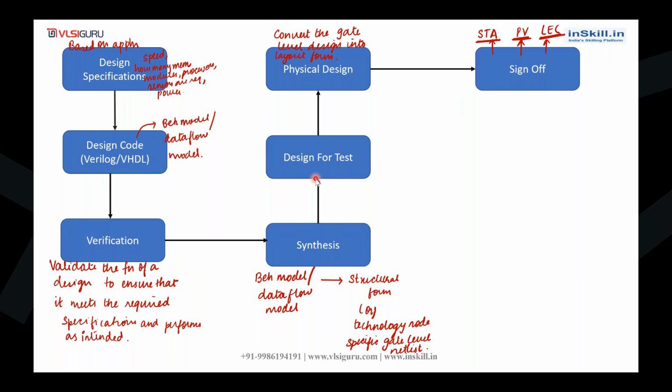And then we have the design for test team, where we will be adding our own structures like scan insertion, memory BIST insertion, and boundary scan insertion. So if you see, in each and every stage, our design is undergoing a lot of changes. That's why LEC is done, to check whether the final design is logically equivalent to the original design or not.